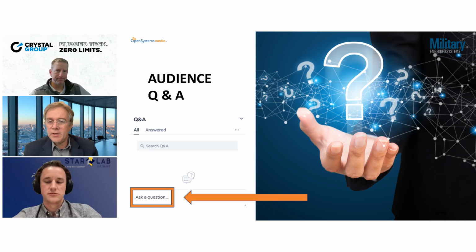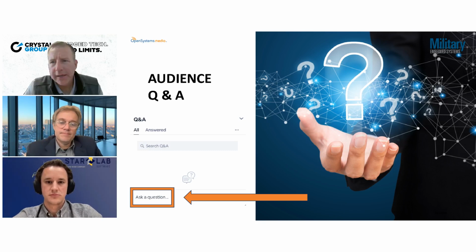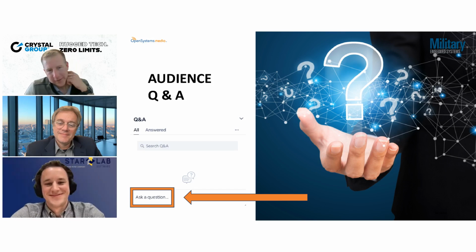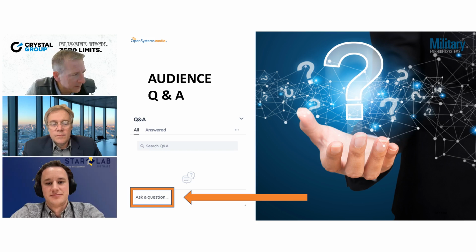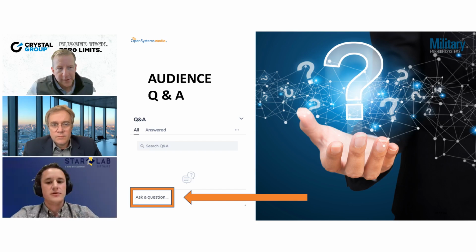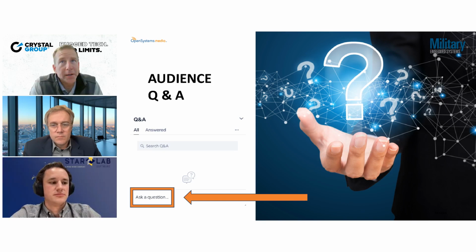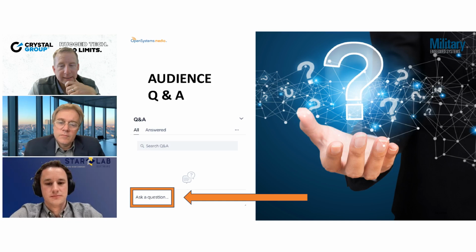Okay. I got a question here for Kale. What are some hardware design considerations when implementing your Crystal Rugged's tech on autonomous platforms? I think, to quote Matthew, it depends. It's really going to be a couple of things. Thermal is going to be your big challenge, and then you're constrained probably with the size of the boards and the parts that you're integrating. The challenge is going to be how do you satisfy the expectation of a small form factor, which is going to drive the density and get the heat out. And so a lot of what goes into our design in terms of ruggedizing it is going to be figuring out how do you design for structure and for thermal management.